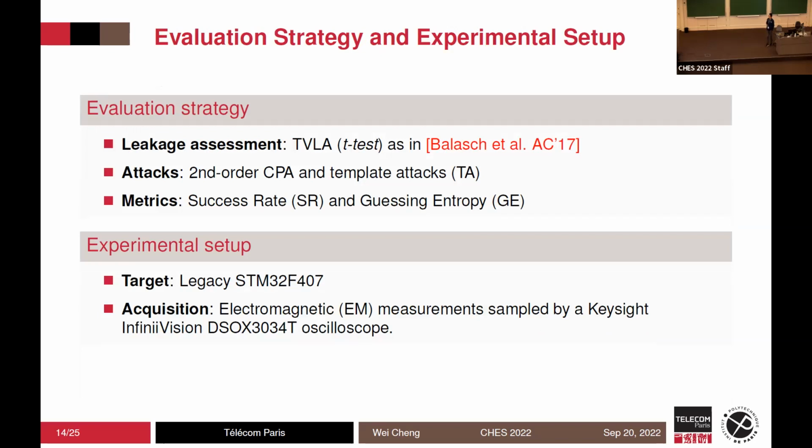For the evaluation, we consider TVLA as the leakage assessment, and for the attacks we consider second-order CPA and also the template attack. For the experimental setup, we choose the ARM Cortex-M4 device, the STM32F407, and we use EM traces.